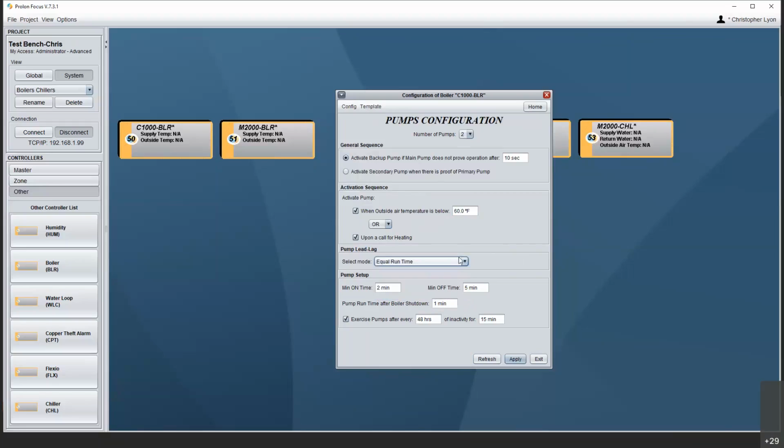Problem is, if you have a situation like where I live, about the 3rd week in November, this pump will turn on and it won't shut off until sometime in March, usually. So if it never reaches a criteria to shut off, it is never going to rotate, and you will essentially end up with no rotation. That's where we bring in the fixed runtime, where if we have a continuous run sequence on there, we're going to force the issue of, okay, every 24 hours of runtime, you will rotate. Okay, so this is, of course, all adjustable.